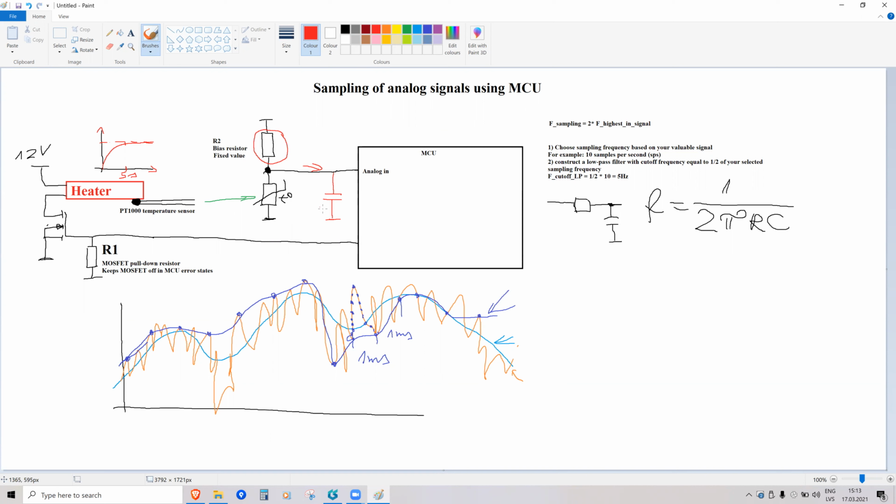So to charge this capacitor, the current will flow through this top resistor. So some resistance you already have. So you actually can reduce this resistor's resistance by the top resistor value. And oftentimes, this is actually how people do it. They just put a capacitor here, and for this RC filter, the top resistor is already the resistor that is used.